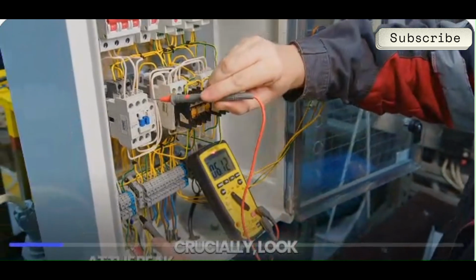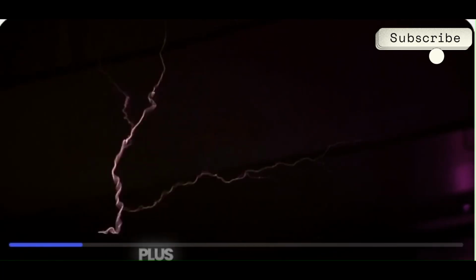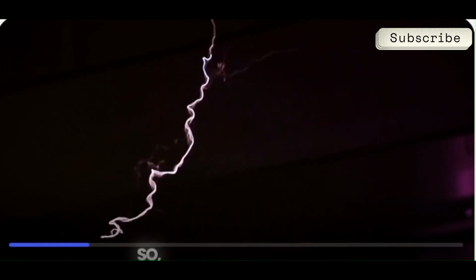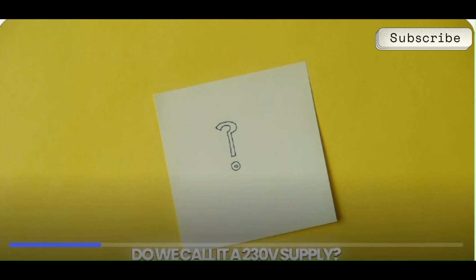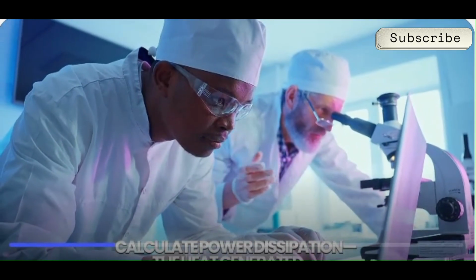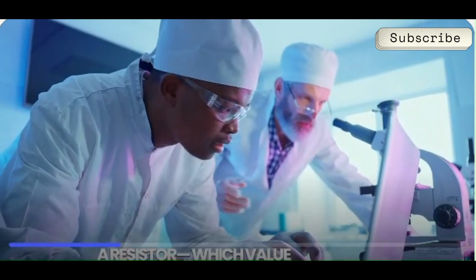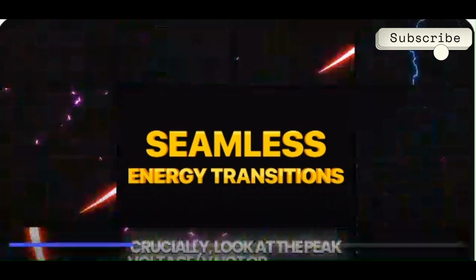Crucially, look at the peak voltage, V0 or V peak. It's not 230 volts. It is actually reaching approximately plus and minus 325 volts. So if the peak is 325 V, why do we call it a 230 V supply? And more importantly, if we want to calculate power dissipation, the heat generated in a resistor, which value do we use?